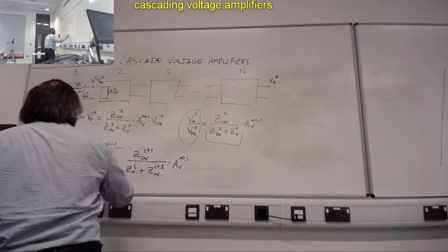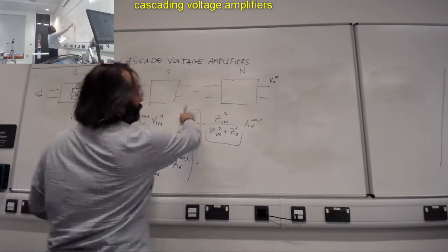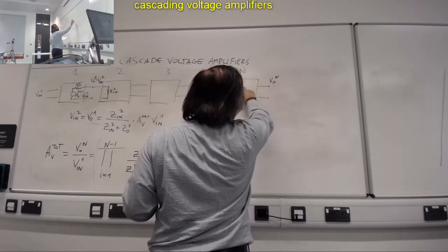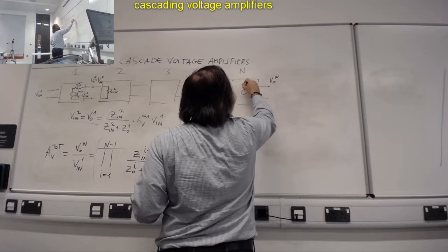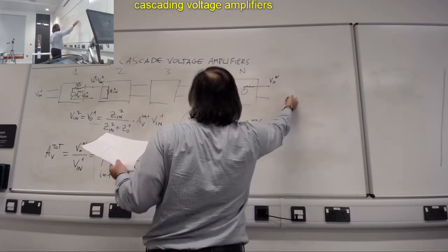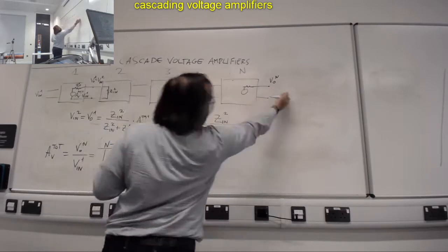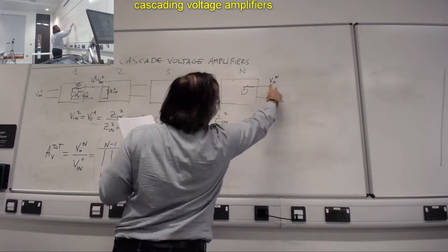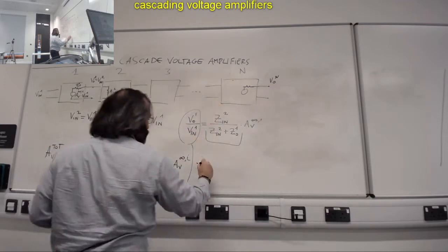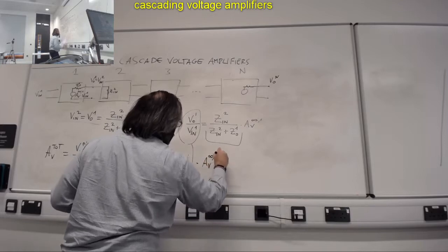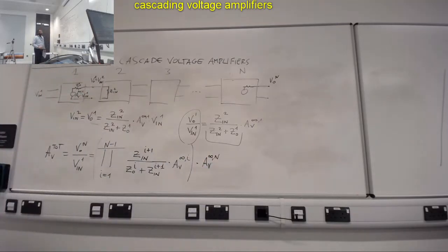All this time, for the last bit, there is nothing attached. So there's no resistor. The resistor is infinite effectively. And so if the input resistor on this side is infinite, the voltage you see is actually the voltage from that. So that remains unaffected. So this is the formula that should work.